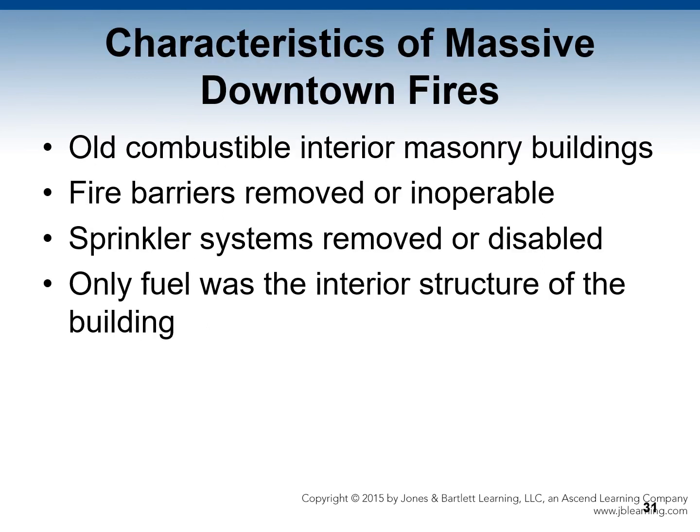Characteristics of massive downtown fires: old combustible interior masonry buildings that were being remodeled, and sometimes these are buildings that were usually wide open where fire barriers were removed or inoperable. Sprinkler systems had been removed or disabled, and the only fuel was the timber interior structure of the building.